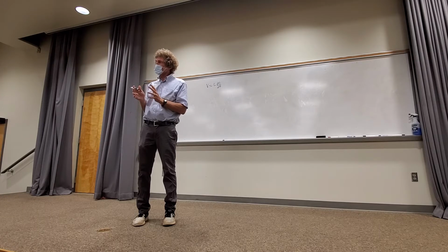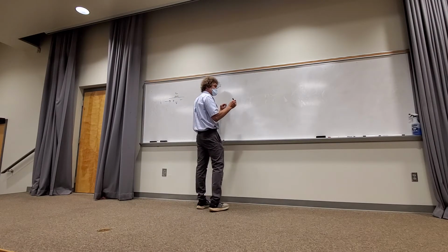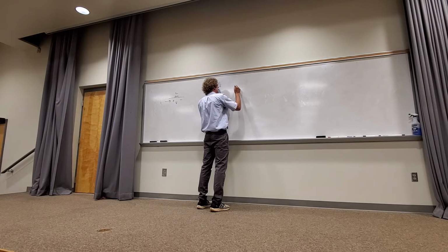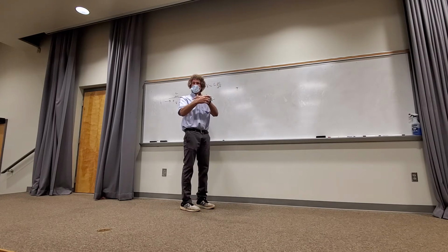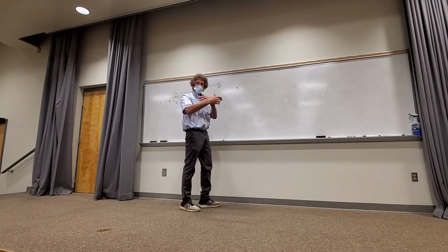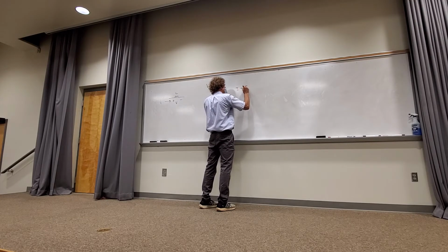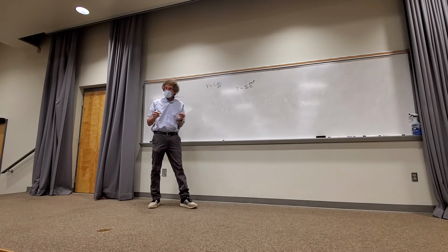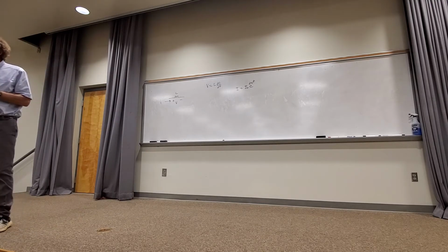Remember, we were moving into what is termed the phasor domain. We're going to assume instead of cosines or sines, we have this e^(j omega t) as the forcing function. So here's what happens. I'll do it in the time domain. The current will respond at the same frequency as the voltage, so it'll be some I naught e^(j omega t). Y'all follow me? Now, remember, e^(j omega t) is cosine of omega t plus j sine of omega t. We only care about the real part, but just bear with me.